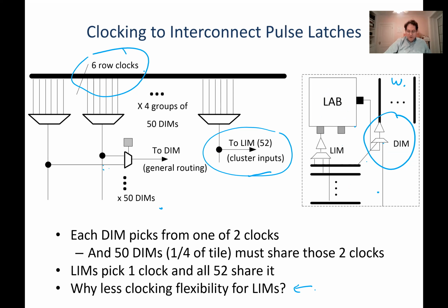The DIMMs are different, right? Some of them could be driving a signal that just came out of this logic block. Okay, so that's going to be on the same clock domain as this logic block. But some of them are going to be driving signals that are just flying by, right? So this signal might have come from halfway across the chip and it's just flying by here. There's no reason to believe it's on the same clock domain.